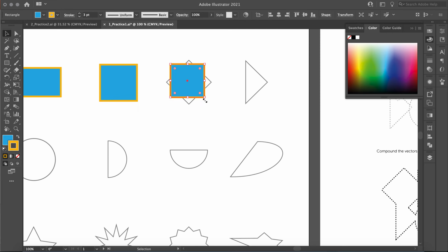I'm not going to make this bigger or smaller. I'm going to step backwards. So I'm going to press Control Z. And then I'm going to go here and I'm going to rotate this. I can rotate this by rotating it like this, where I'm rotating it 360 degrees. I can also hold my Shift key, and it'll rotate this 15 degrees here.